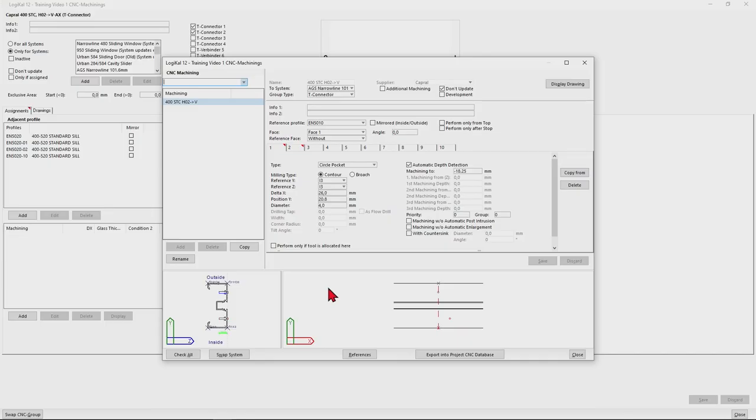For this machining detail, you will actually see that there's two options available to you, two holes in this detail. You will then need to modify the diameter on each hole to suit your tools available. For this example, I will change that to 5 mm for the first hole, and also need to do the same for the secondary hole. Click on Save to update your detail.